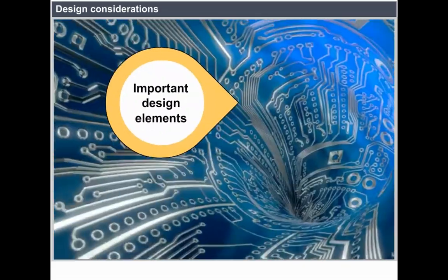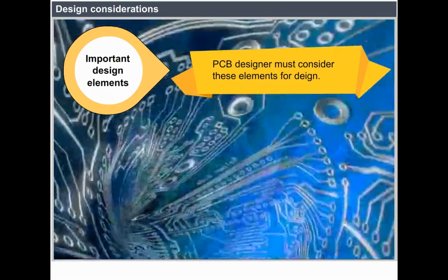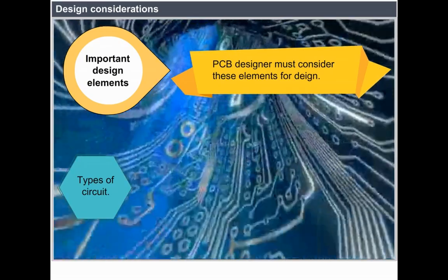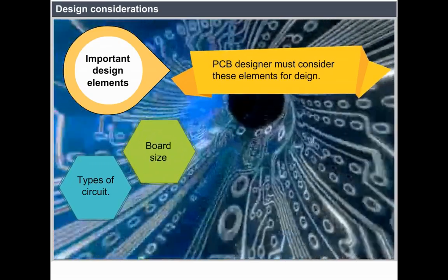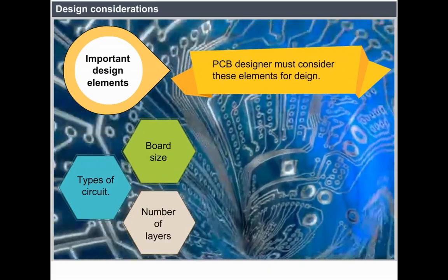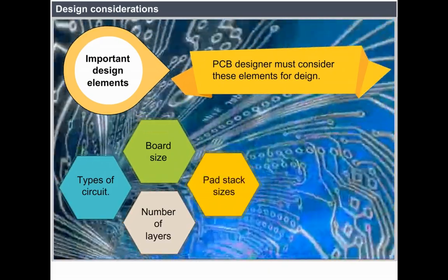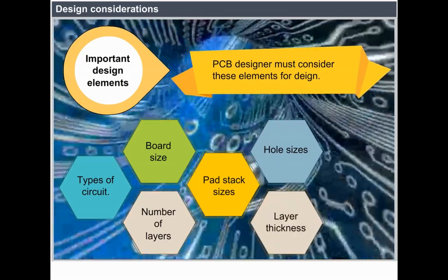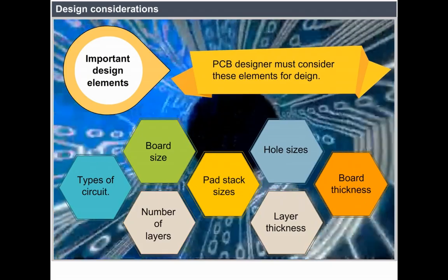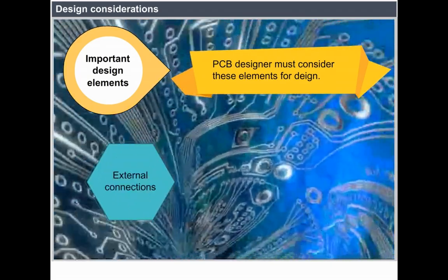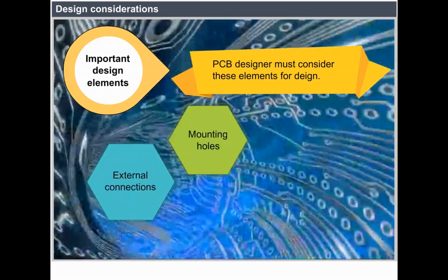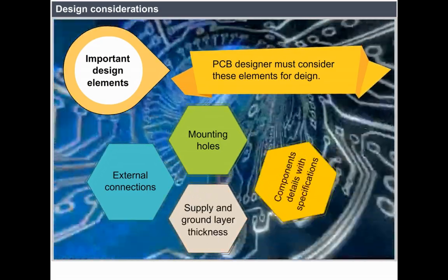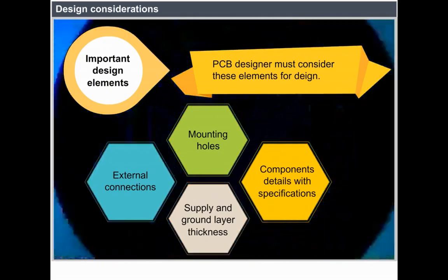Important design elements. The PCB designer must consider these elements for design: types of circuit, board size, number of layers, pad stack sizes, hole sizes, layer thickness, board thickness, external connections, mounting holes, supply and ground layer thickness, component details with specifications.